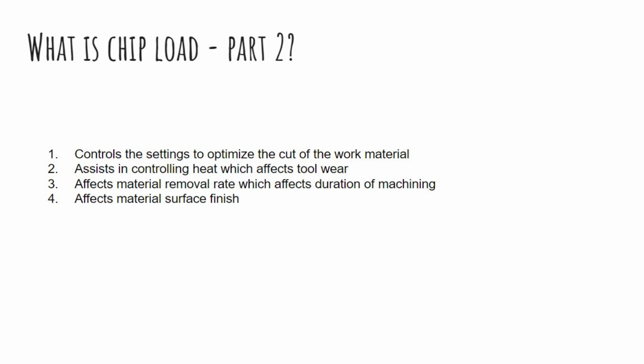On the other end, running high speed with high rates of travel through the material may also produce extra heat. So what we're looking to do is give us the best cutting with the best rotational rate so that we don't overheat our bits. Okay.